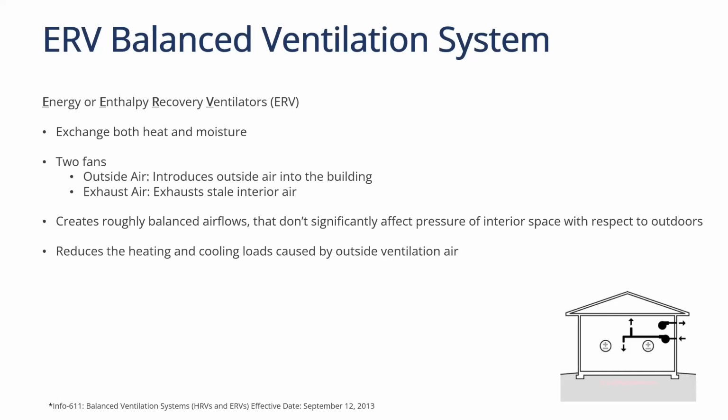And the real benefit is that it creates that balanced airflow, but it does not significantly affect the pressure of the indoor interior space, where some of the other units, if you have just supply or just exhaust, then somebody's got to make sure that once all those components are installed, that it's balanced and you have the proper pressure inside the apartment.